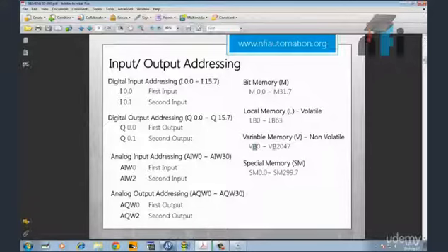So B is for byte addressing. If your information is only up to 8-bit, use VB0. If your information is up to 16-bit, you can use VW0. If your information is 32-bit, you can use VD0. So it's VB, B for Bangalore, then you have VW, you can see the W here, then you have VD, D for Delhi. So you have VB0 to VB2047 non-volatile memory registers.